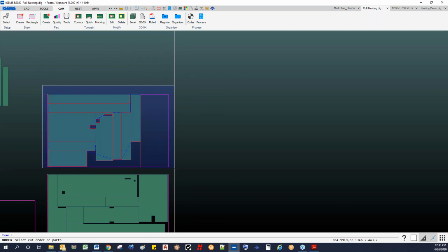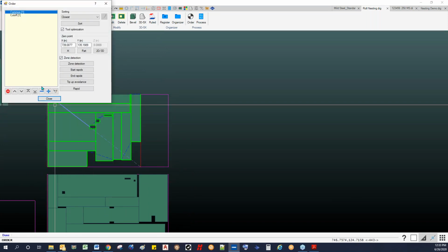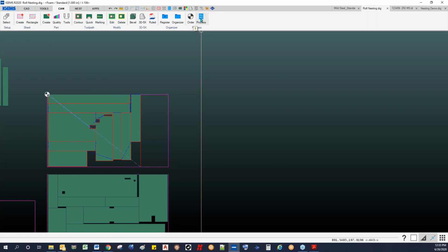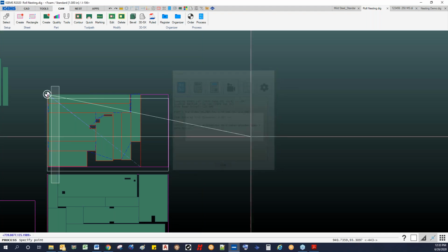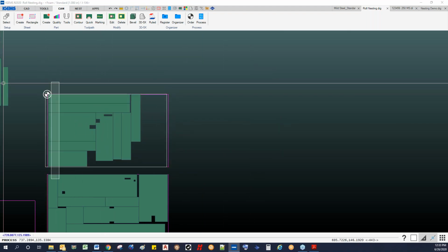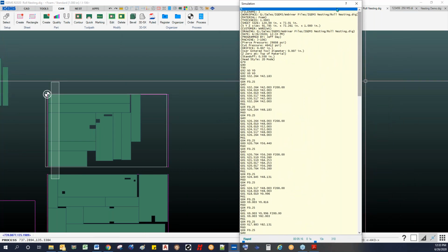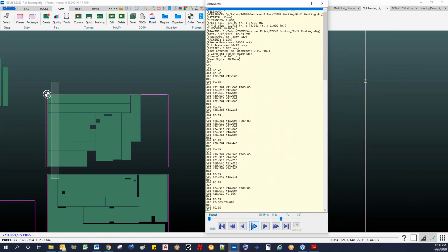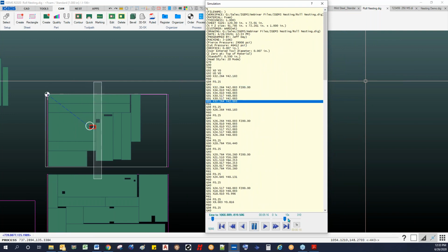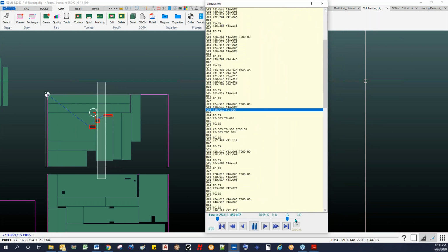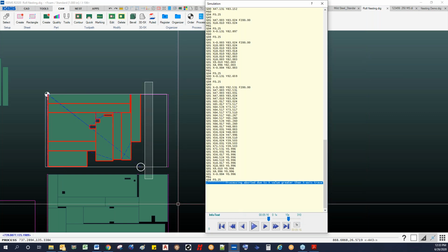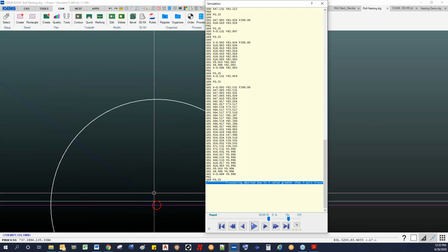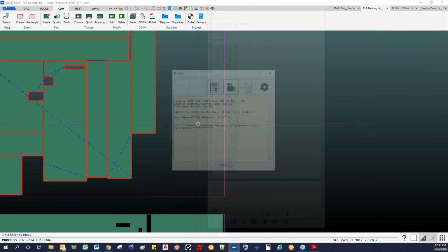So if I add my 0 point on here for my sheet, it's got the common cuts that it'll do, and then it'll do the cutoff. So let's take a look at what this is going to do on our simulation. And let me resize this here a bit. So all of those are common cuts. And then I drew my line a little bit too long there because I had that error message, but at this point here it would then cut up across that point there.